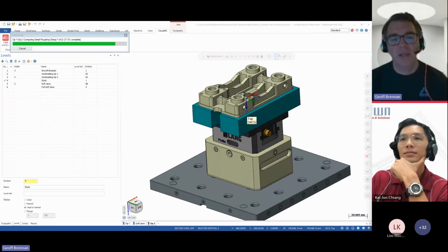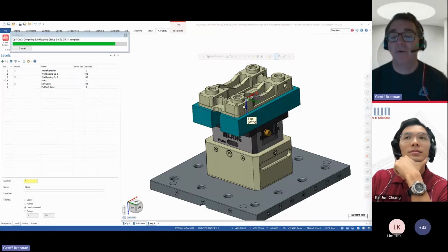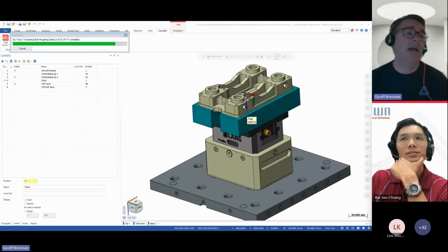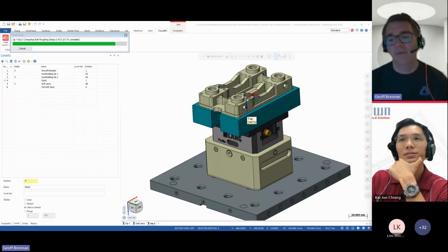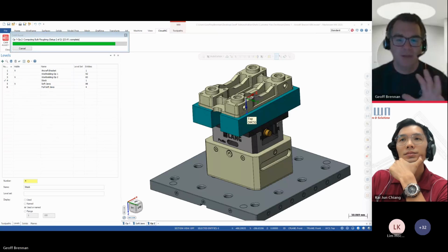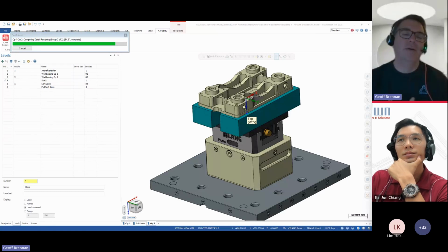Sort of in the longer term, we hear a lot about other machining applications. Currently, of course, Cam Assist is really specialized on milling, and that's 3-axis and 3+2. When we say 3+2, we really mean 3-axis for 4-axis and 5-axis machines, where the part is put in an orientation, and then a 3-axis toolpath is created for that orientation, and we can have many orientations, of course, but it's not doing dynamic, continuous motion, true 5-axis machining at this point.